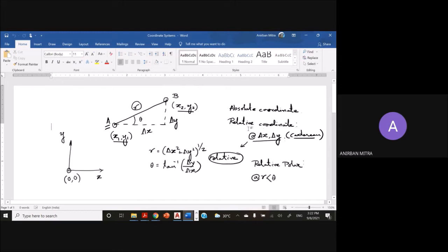But if you put this @ symbol and go for relative coordinate system, then the previous point that you had just marked is going to act as the reference point. So if you have already indicated what point A is, that now becomes the reference. With respect to that, the point B is going to be defined.